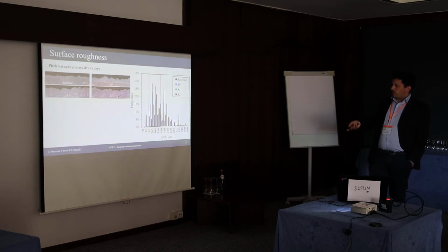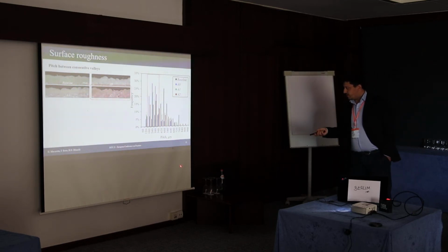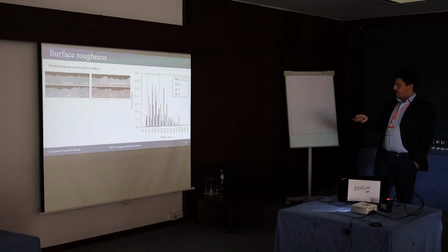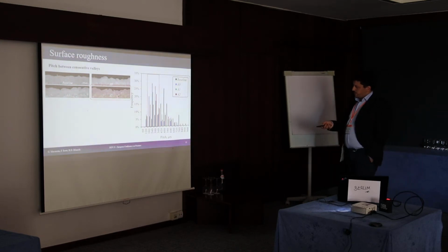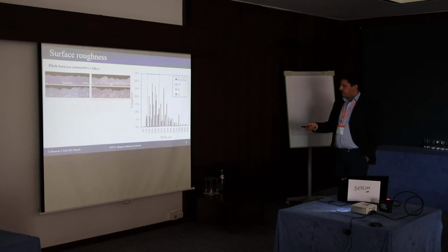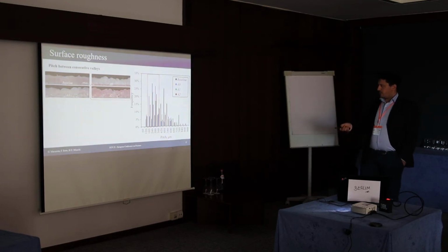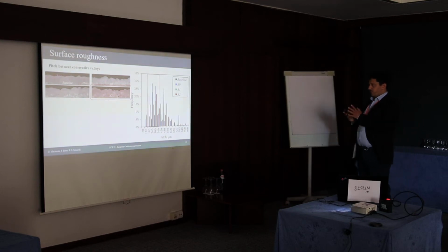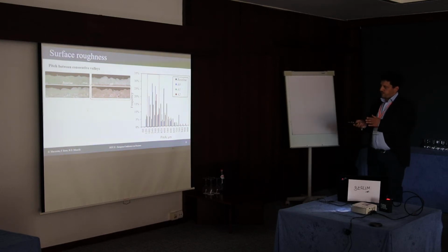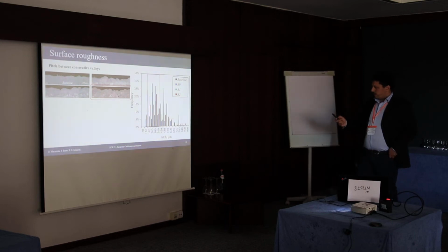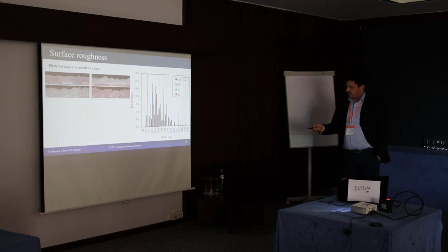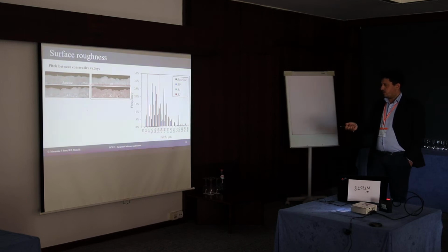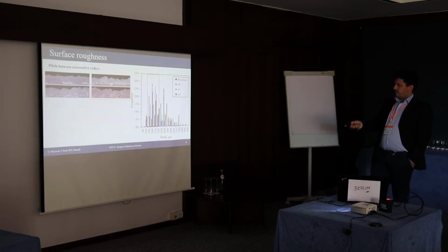When we move to A1, A0, A1, but in particular A2 parameters, we see that the more frequent value is lower. It's about 240 microns. But we continue to observe higher pitches. So we have a superposition of a short pitch. Here you have to consider that the layer thickness is 60 microns. So here you have something that is 4 times the layer thickness, while you have here that is 6 times